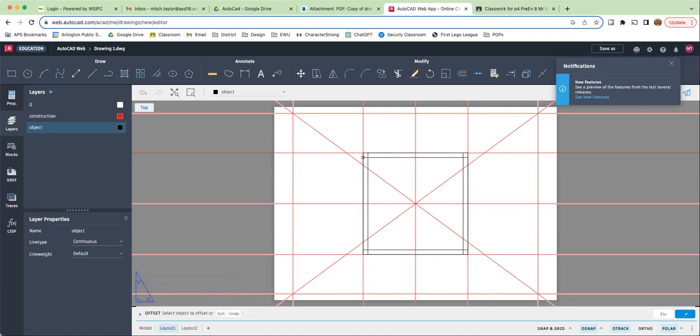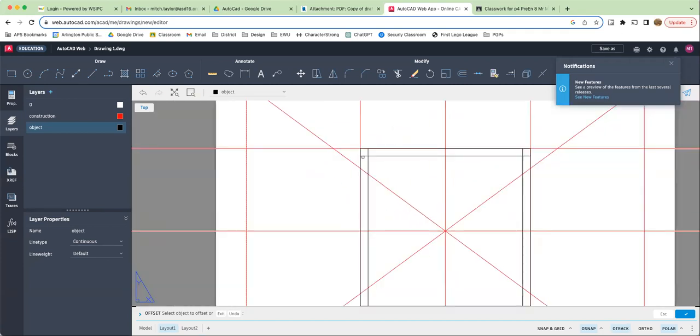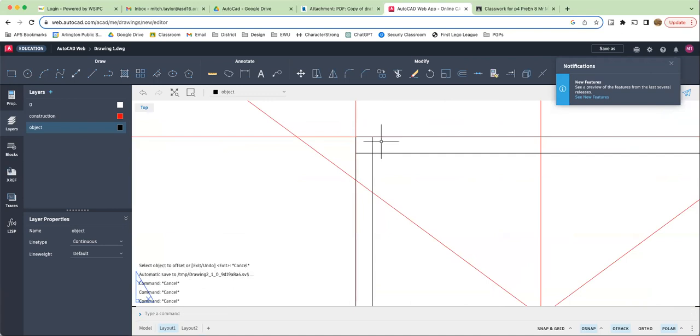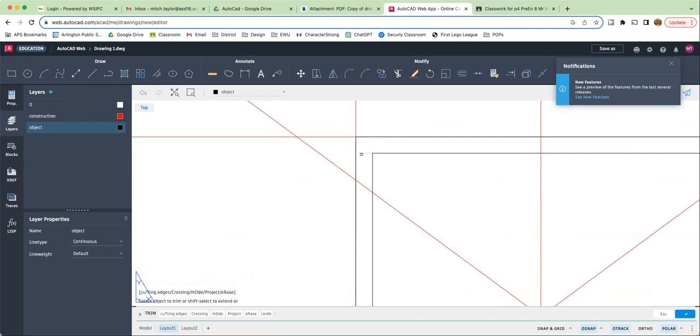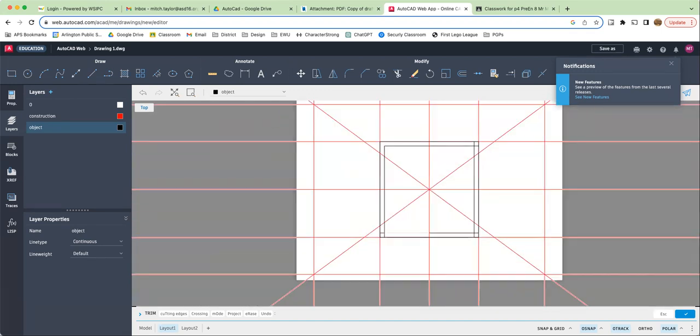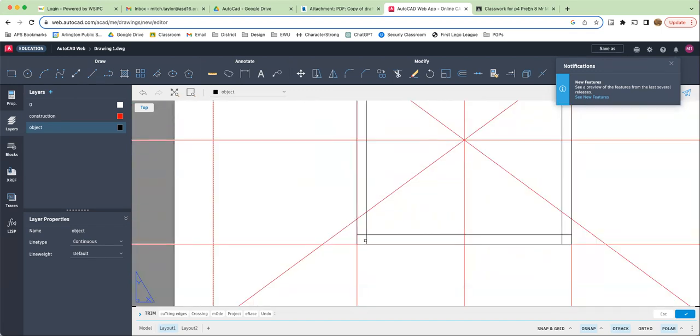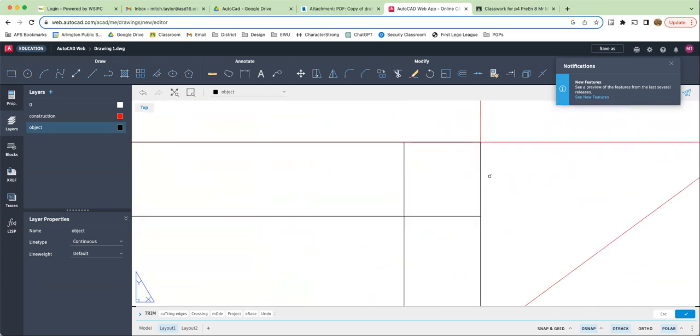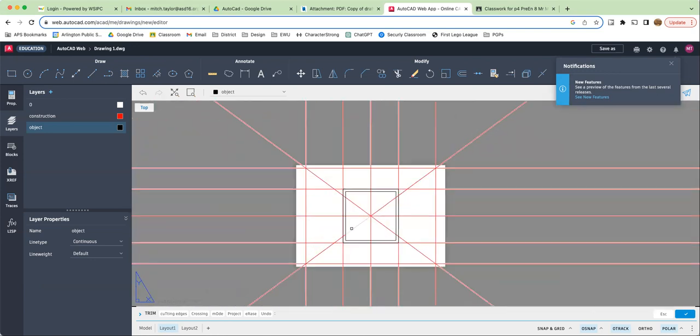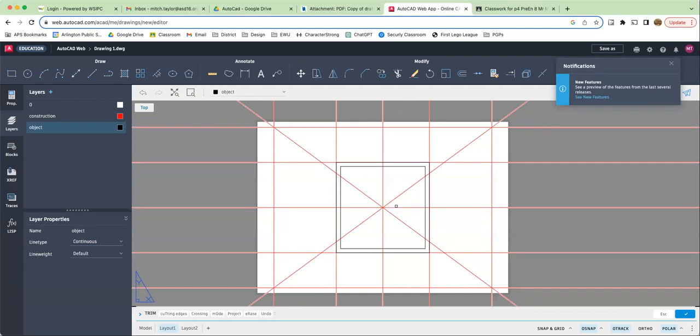At this point, we can zoom into our spots and we will use another function. Let's hit escape. And we'll use what's called trim. Type in trim, mouse over, and we can trim and simply and easily erase those out. Trim that, and trim each of our spots. Okay. Now let's get set up again, exactly where we want. Zoom in and out with 2 fingers on your trackpad. And now I've got the outline for my chessboard.